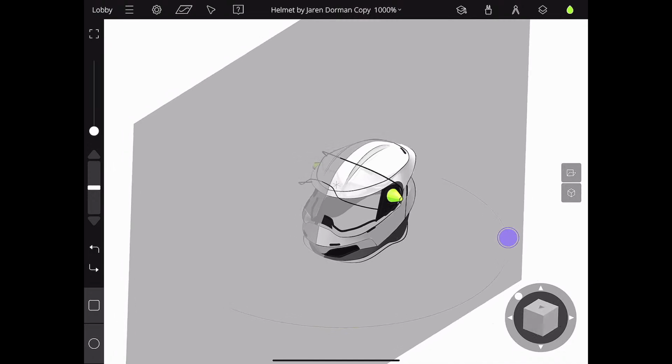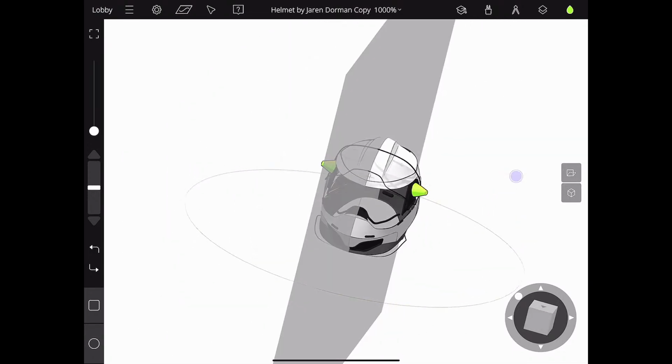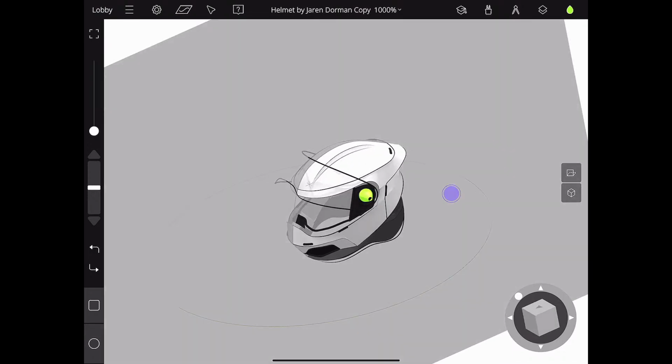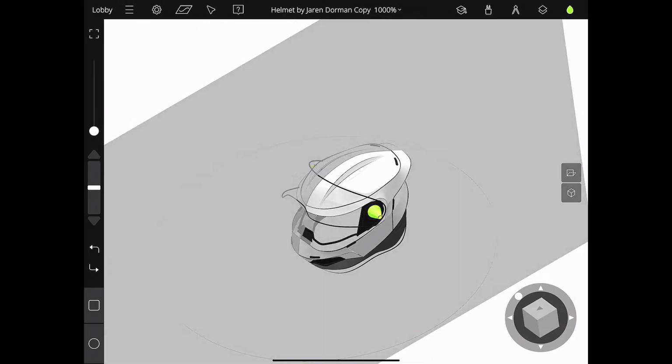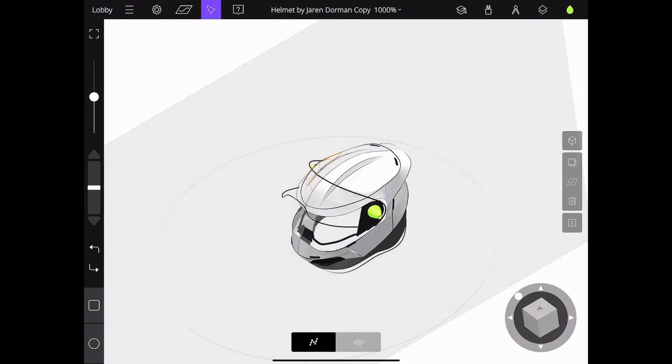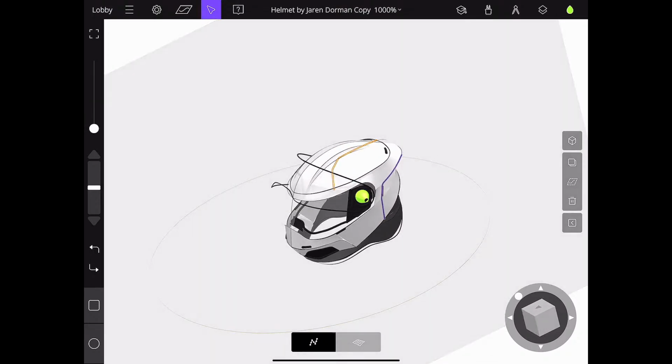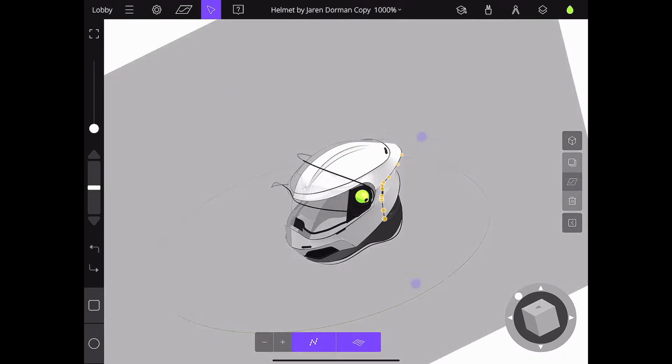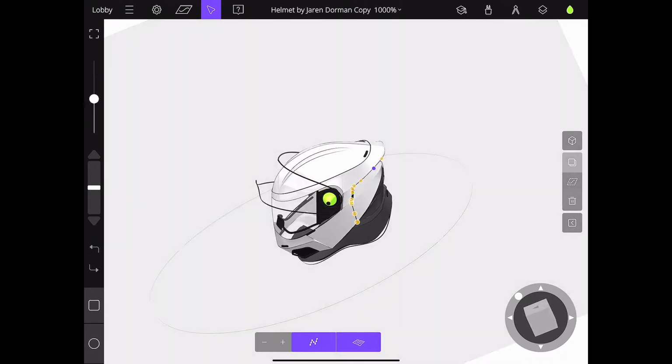So removing control points. Let me just go over that one more time. It says thanks for not knowing how to remove them. Maybe that's a typo, but just so you know, in order to remove them, we go into edit mode and we click the dotted icon here, and so you see we have points. All you've got to do is select a point and then hit the little trash can over here at the top, at the right side, and that'll delete that point.